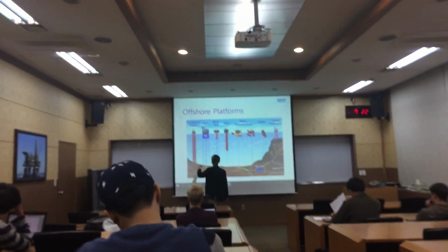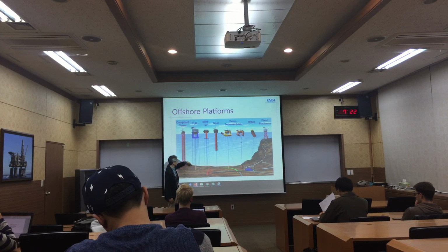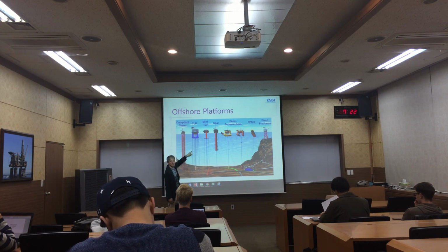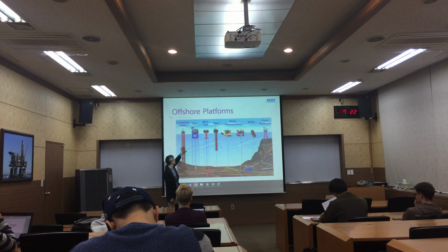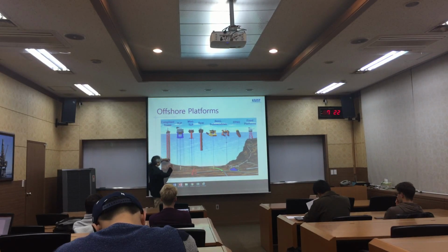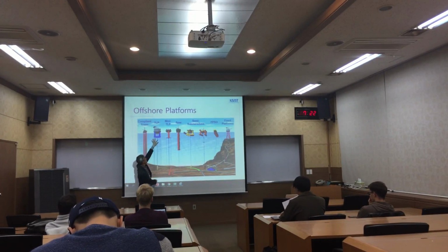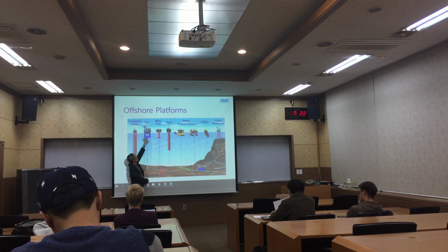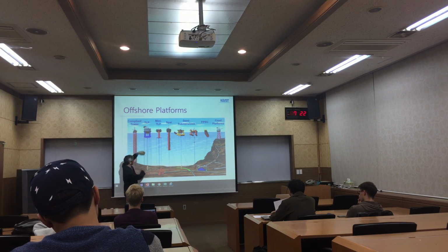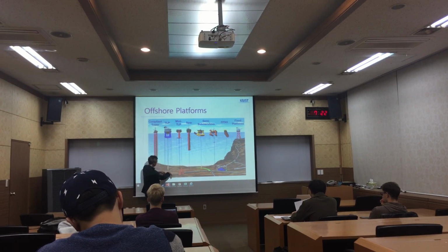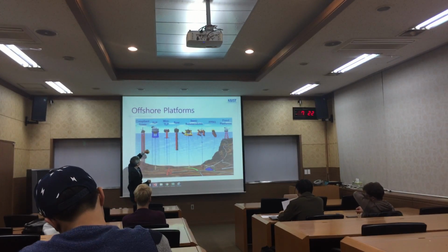You have a very strong, how can I say, mooring line. We call this tether, so that this has a very big tension. So it's almost like a structure, but it is all tension. This is a compression, right? But this is a tension. So this one has floating buoyancy more than structural weight, so that tension is coming from grabbing from the root, so anchoring, and also floating power from the buoyancy. So tension is going on.